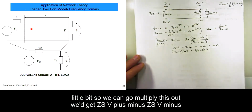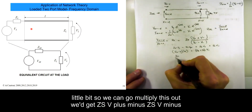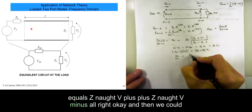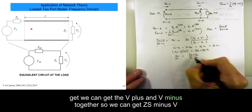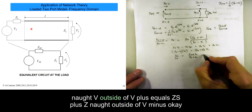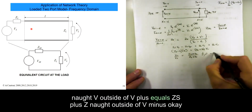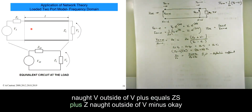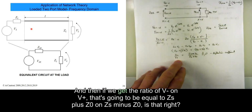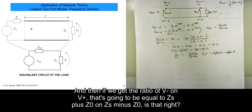So we can multiply this out. We'd get ZS V plus minus ZS V minus equals Z0 V plus Z0 V minus. Is that right? And then we could get the V plus and V minus together, so we get ZS minus Z0 outside of V plus equals ZS plus Z0 outside of V minus. And then if we get the ratio of V minus on V plus, that's going to be